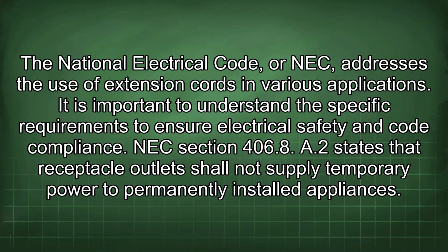The National Electrical Code, or NEC, addresses the use of extension cords in various applications. It is important to understand the specific requirements to ensure electrical safety and code compliance. NEC Section 406.8 A2 states that receptacle outlets shall not supply temporary power to permanently installed appliances.